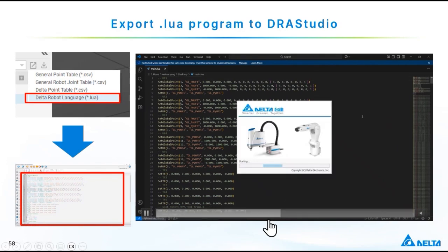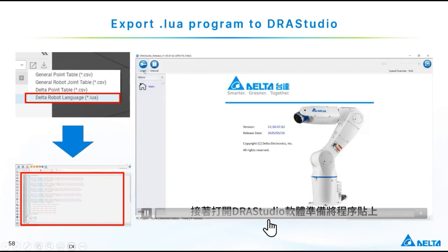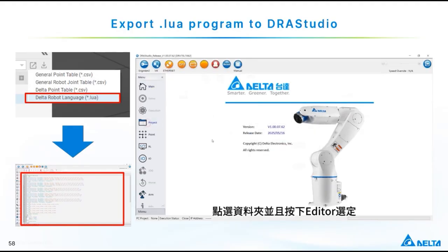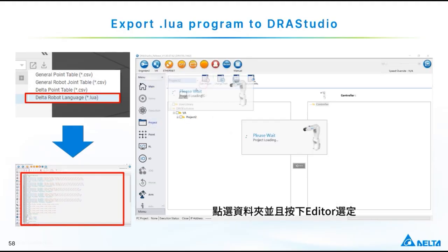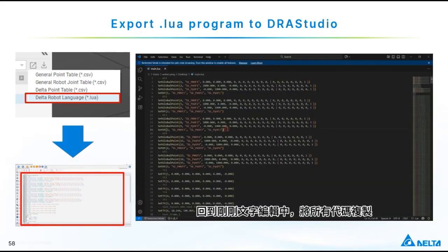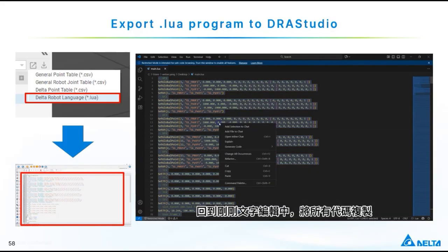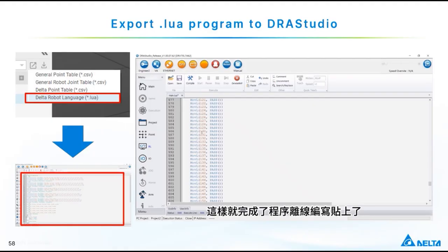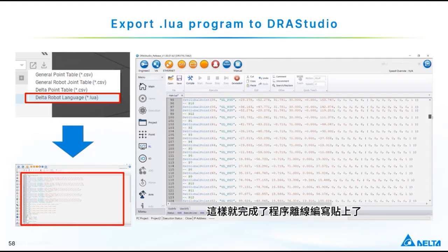We only have to make sure that the user frame is the same as in the virtual environment, which means that if we output a project with user frame 1, the only thing we need to do is calibrate the user frame on the real robot, so we can directly run the whole simulation without any problem.